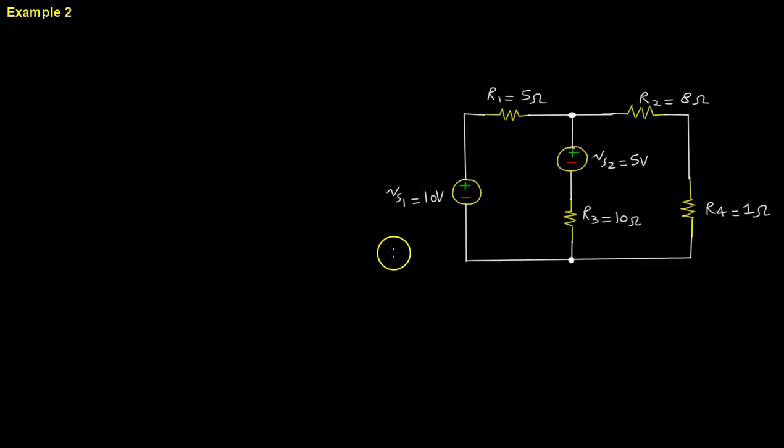So given the cookbook recipe given in the first example, we can go ahead and apply the same principles and find the mesh currents here. Looking at this circuit, you can see there are two different voltage sources at two different places, there's no current sources, of course, and you have some resistive networks. And applying KVL is going to help you find the element voltages.